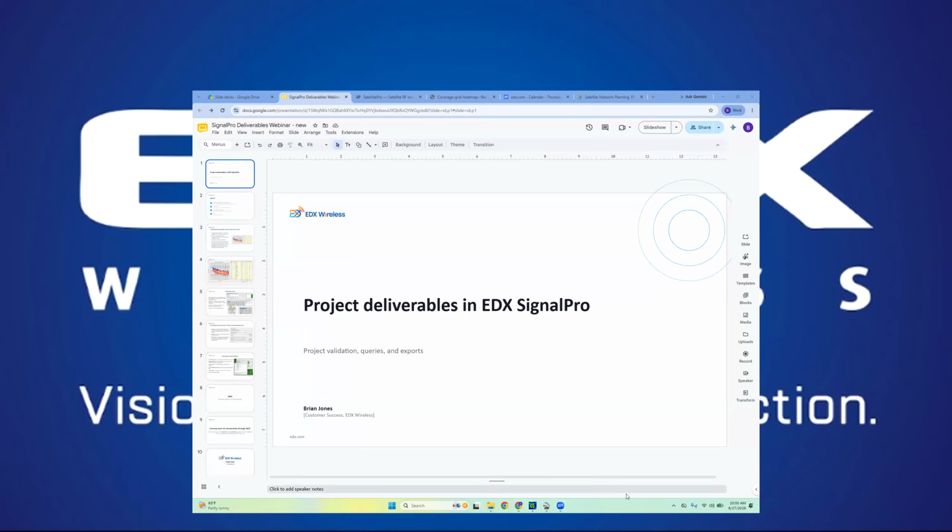And again, in case you haven't looked at this dialog in a little while, we've got multiple different prop model settings within a project, so that I can create one set of settings on this line and then another set of settings on another line. So maybe if I have a rural area of the county that I want to cover with a different prop model than my downtown urban core, I can set those up here and assign those to different sectors, different sites in the project.